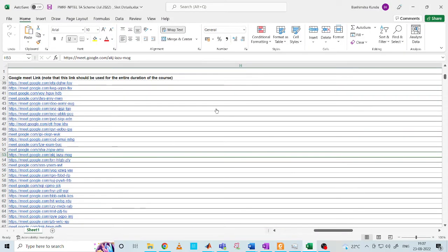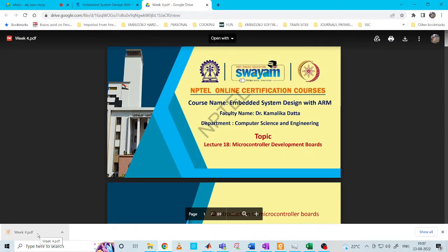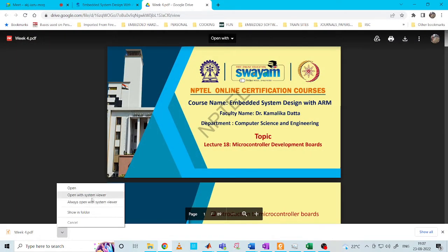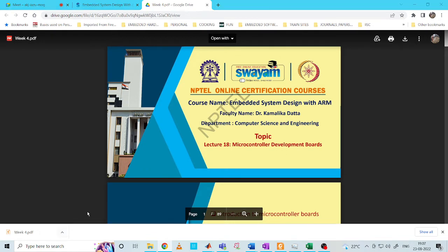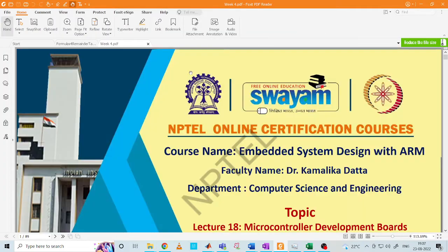Sir, one question. In STM32, whether the analog pins can be used as both input and output? In the STM32 board, we have the analog pins. It is only for input purpose. For output, we are using the PWM out. Is it correct, sir?